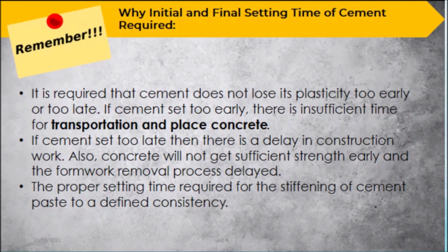So, bakit ba natin ginagawa yung initial and final setting time na test? First, it is required that the cement does not lose its plasticity too early or too late. If cement sets too early, there is insufficient time for transportation and placing of concrete. So, ibig sabihin lang niyan class, through initial and final setting time test ng ating cement, we can determine kung sapat ba yung magiging travel time ng ating mixer papunta dun sa site where we will place the concrete.